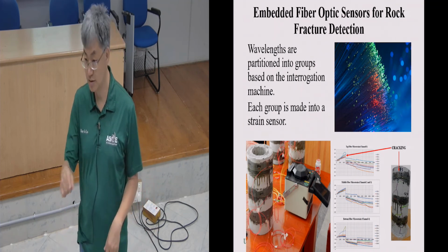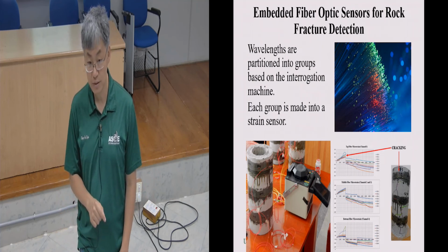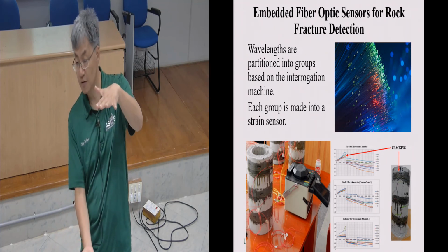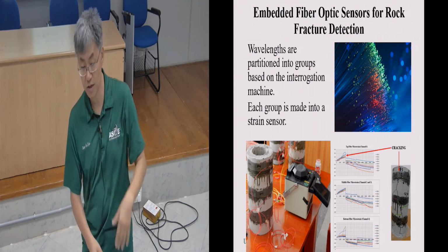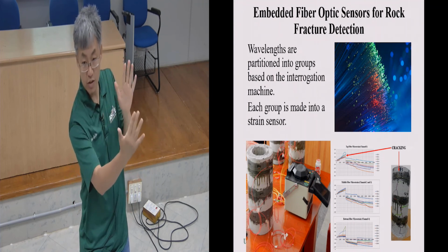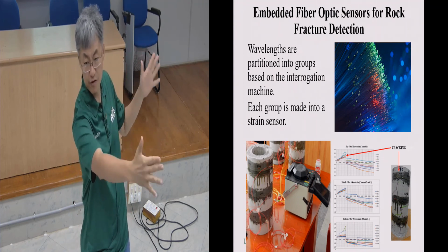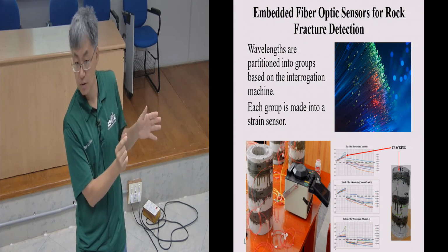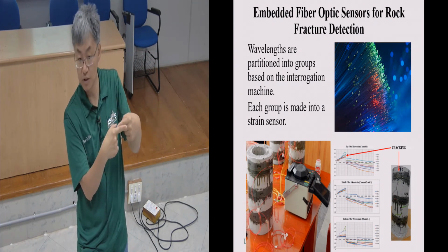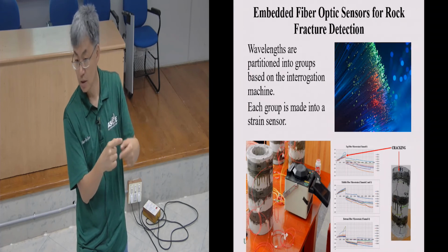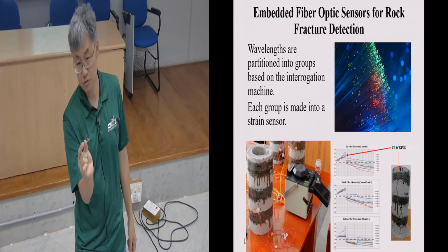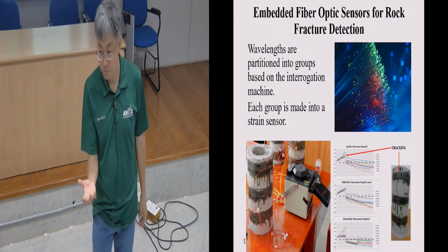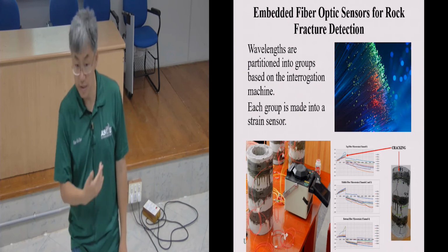I mentioned that the technique has low resolution. For geological applications it's good, because we're looking at several feet of soil or rock change. But when you deal with nuclear concrete, you may have a 3 feet thick wall, but you're looking for a problem that is maybe a micro crack or debonding between the steel and the concrete. Those need much higher resolution. So using that technique, I don't envision you can find meaningful problems, but theoretically, yes, it can be done.